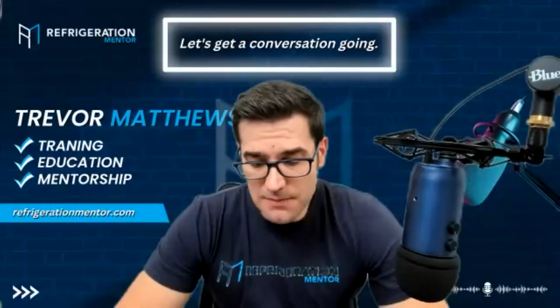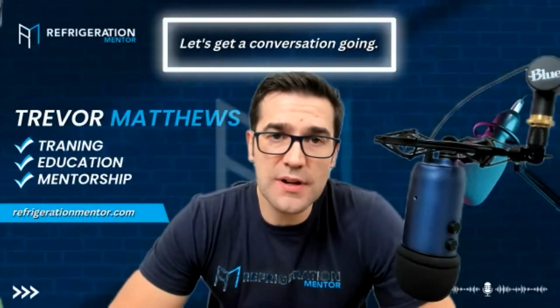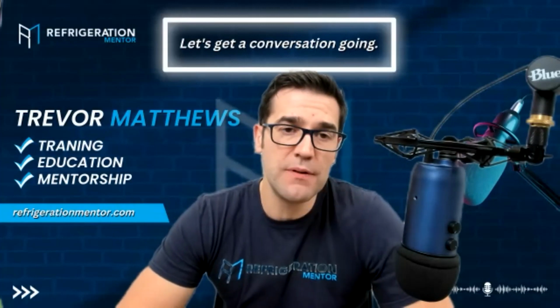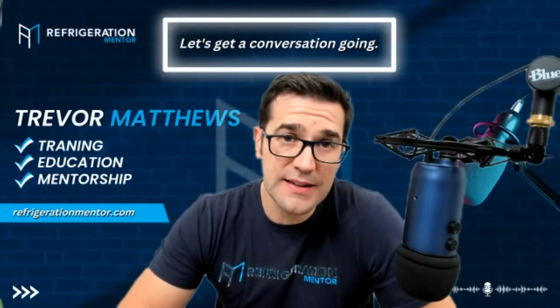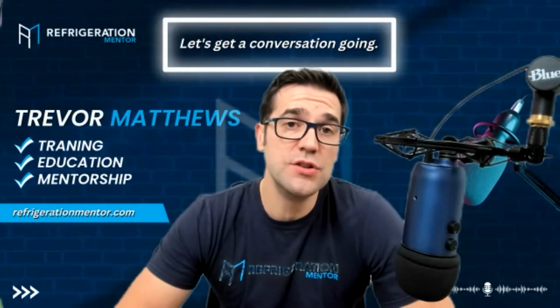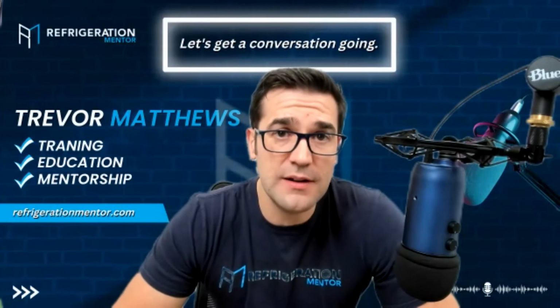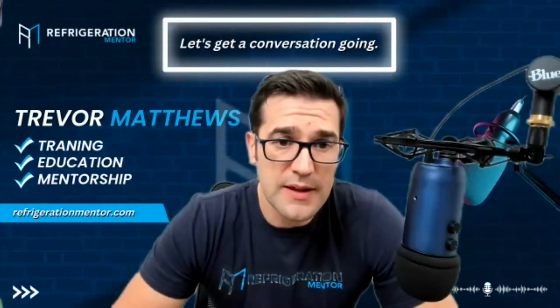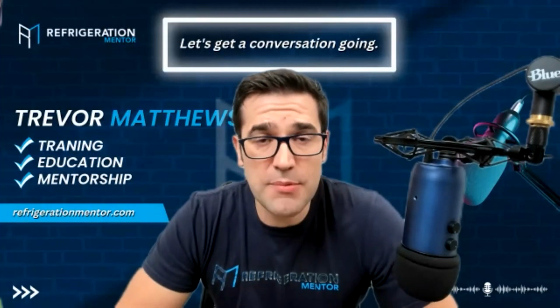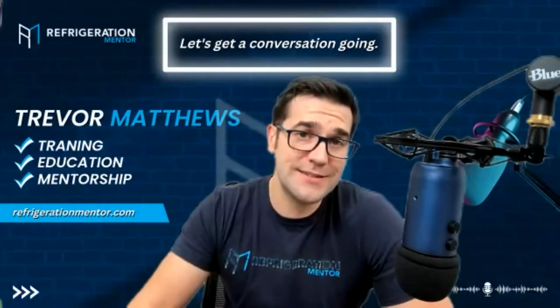Yeah. And I've seen compressor manufacturers over the last 10 years add so many new components to really help prevent that. There's a lot of stuff inside the compressors to help reduce the failures. Copeland put out tons and tons of CoreSense, for example, which has overheat protection and discharge line temperature protection that you can add onto the system.